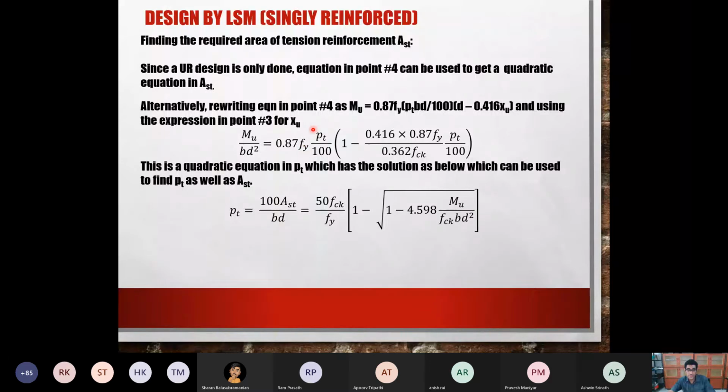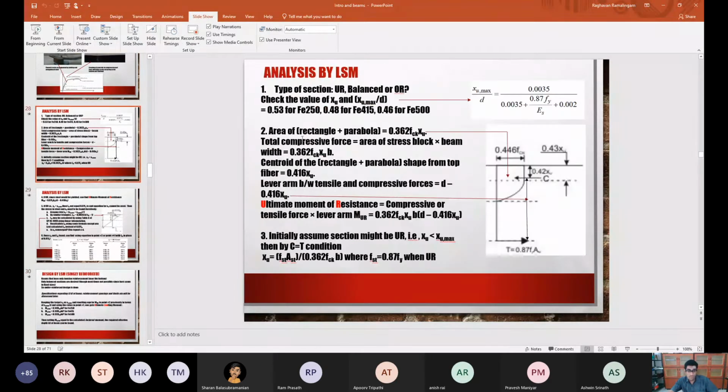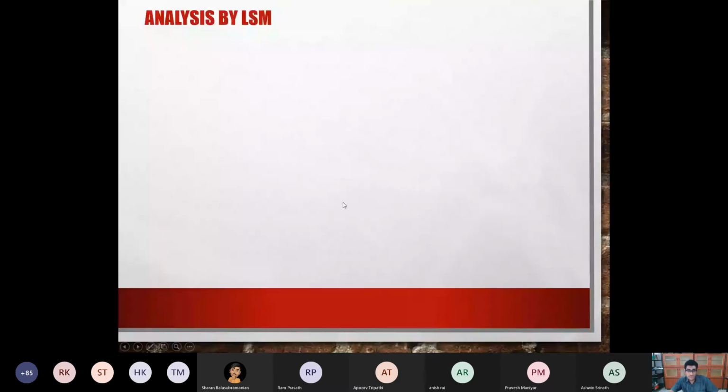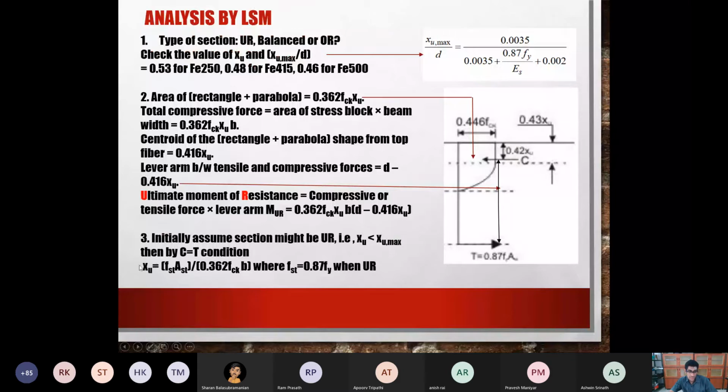okay, if you look, best thing is I just go back. So if you look at this equation, if you have a look over here, you see that in terms of neutral axis, if your area of the beam is increased, okay, or B is increased, if you increase the area of your beam, usually nobody will increase the width, people usually try to increase the depth.